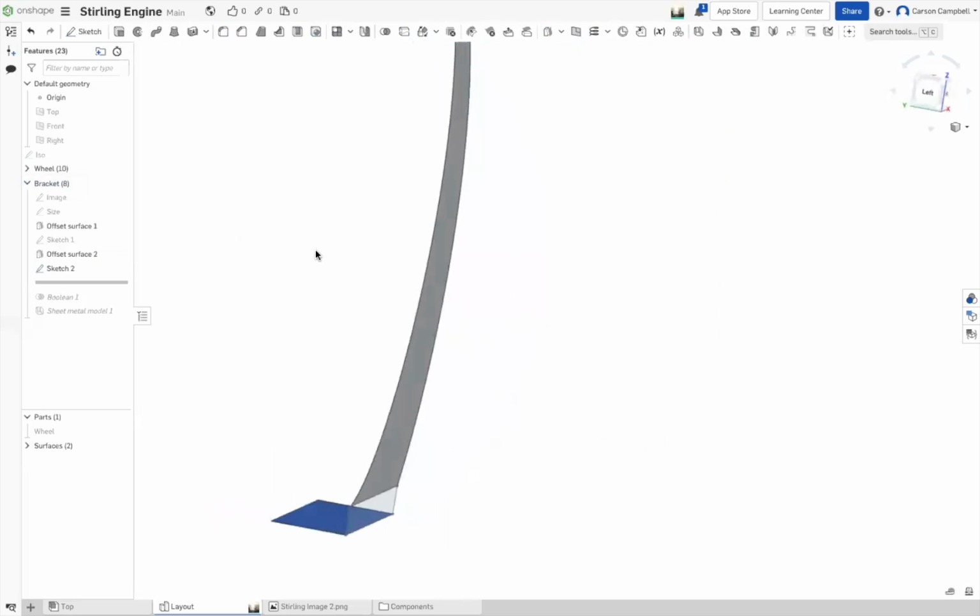And now you've got 2 sheets and you got a sketch. You want a third sheet? How do you make a sheet? No, can't Boolean, not yet. You already have a Boolean, by the way. Offset, you got it. Pick the region. Yep, go 0. Pick the region. Nope, the sketch region. Yeah, that. And say okay.